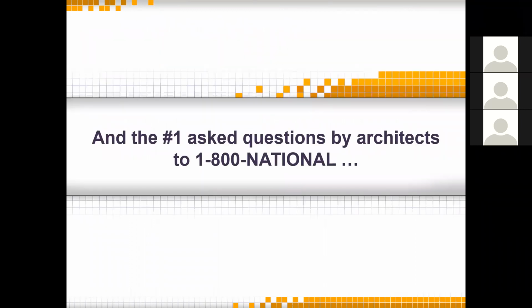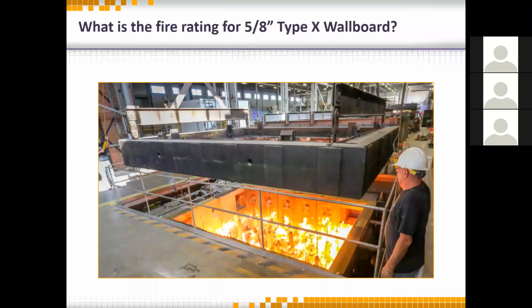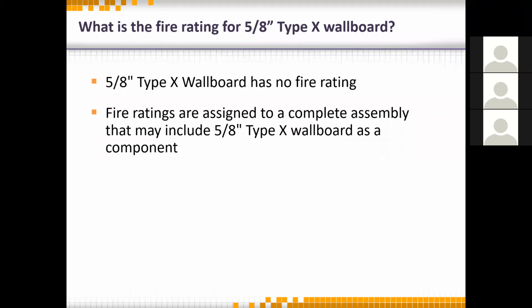Number one question we get at our technical department: what is the fire rating of our 5/8 type X wallboard? Trick question. There is no fire rating for any product. It's all the parts and pieces that were tested, the various manufacturers together, and what's listed in the UL design that gives you your fire rating.